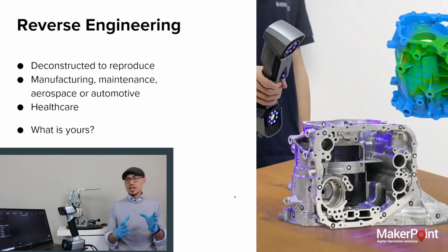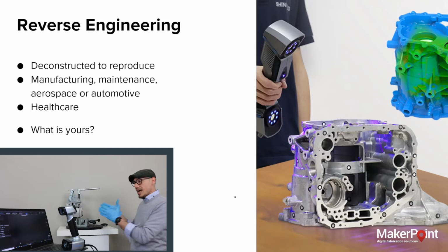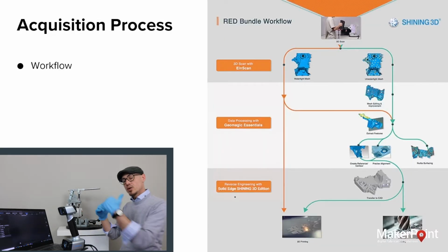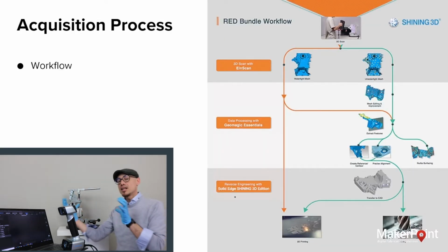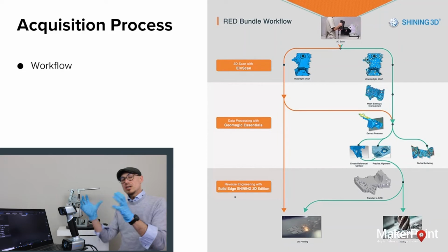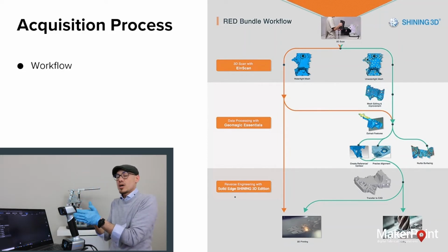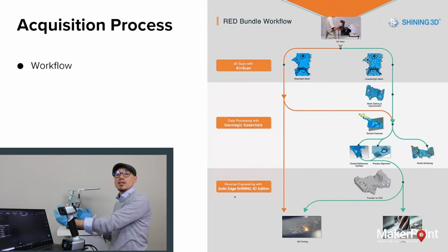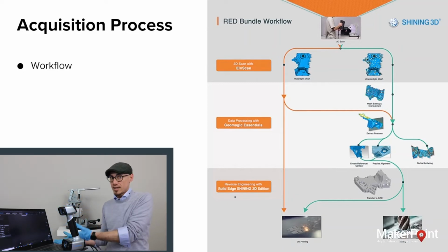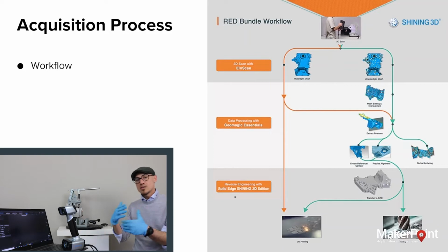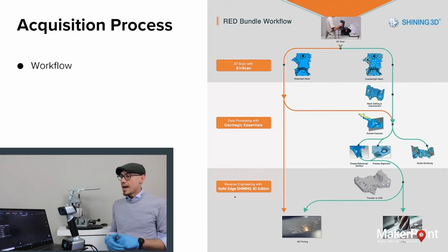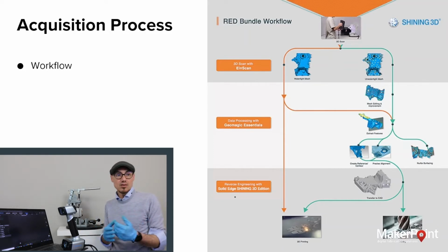So the workflow is: prepare your parts, start scanning. It takes a few minutes when it's well done. Then generate the point cloud. At that moment, you're able to create many layers and then attach them. When you attach them and they overlap, the process is finished. Then you can extract the mesh later on offline, even not at the client. This is a way to be very fast and precise also.